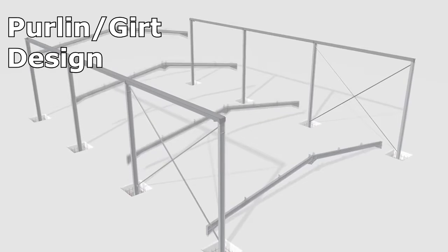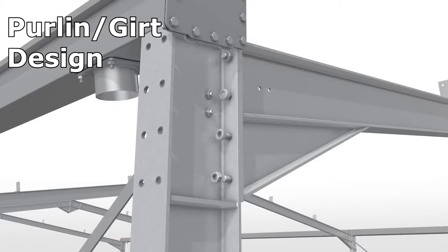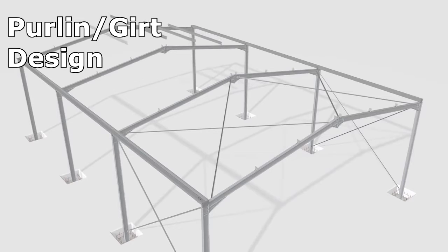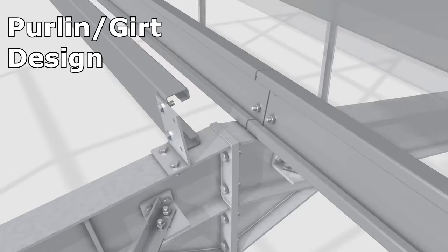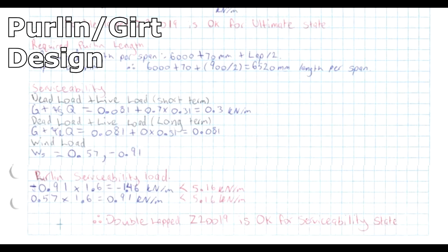To design the purlins and girts, the dead load and live load of the surface must be calculated. A girt and purlin is selected to use. Load combinations are calculated with the critical load combination being applied to the length of the girt or purlin, providing the force in kilonewtons per meter, which can be compared to the capacity tables to check the selected member is structurally stable. The serviceability is then calculated.